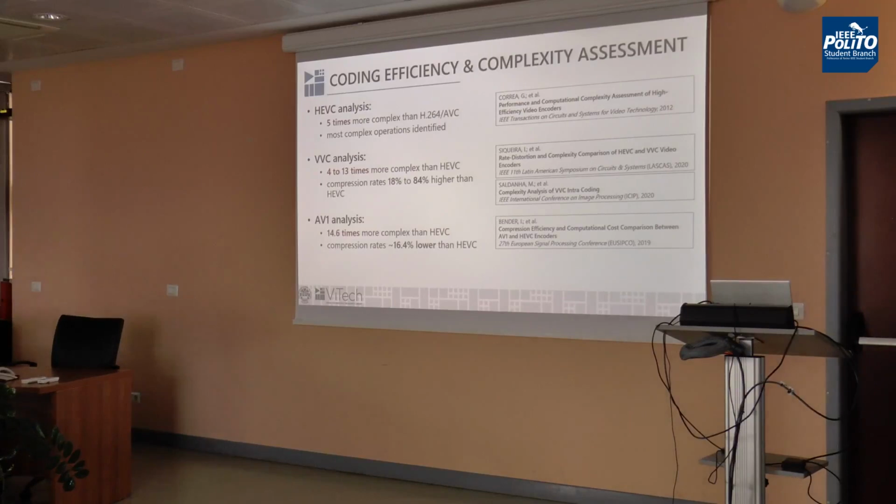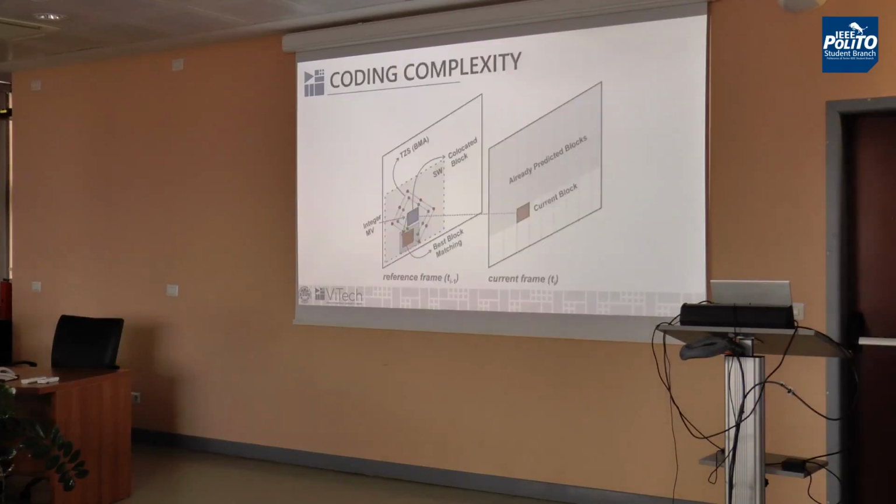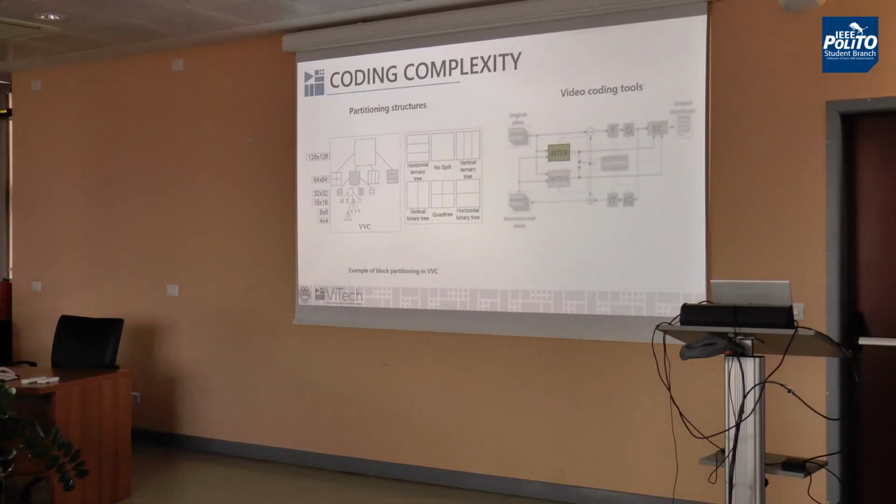When searching in the previous frame, this is the way we used to do it until these days. Now you also have affine motion estimation, which means that in addition to searching in the reference frame, you can stretch it, use geometric transformations to find good matchings. So it's a completely new dimension of search. So you may search for each position and give a grade, and do this iteration in that encoding loop many times.